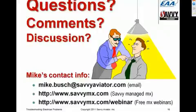All right. What's your guideline in terms of resetting popped circuit breakers in flight? Well, that's an interesting question. The general rule is you reset it. You wait a little while for it to cool off. You reset it once. If it pops a second time, you don't screw with it. We don't want to get into the Ricky Nelson syndrome.